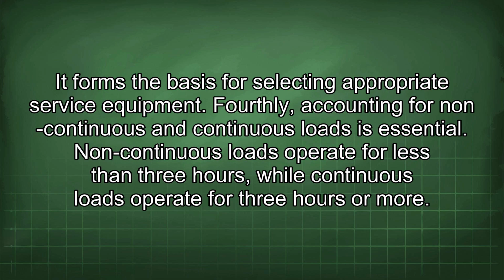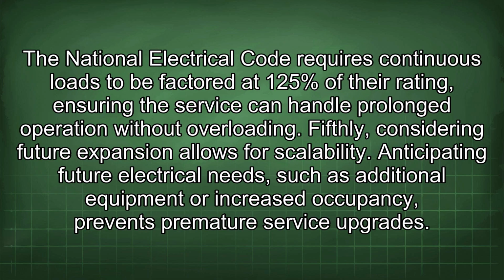Fourthly, accounting for non-continuous and continuous loads is essential. Non-continuous loads operate for less than 3 hours, while continuous loads operate for 3 hours or more. The National Electrical Code requires continuous loads to be factored at 125% of their rating, ensuring the service can handle prolonged operation without overloading.